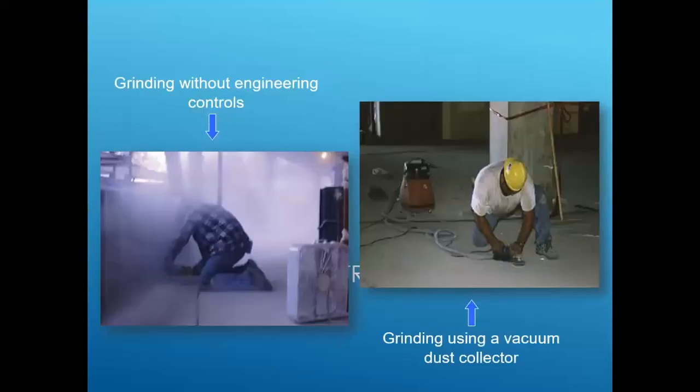Similarly, we see an employee grinding on concrete without engineering controls on the left. And on the right, they're using a vacuum dust collection system attached to the grinder to limit the fugitive dust.